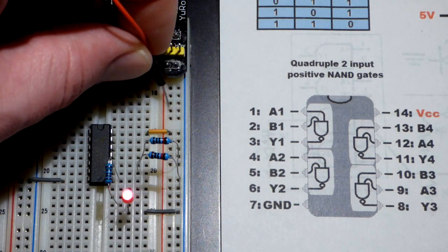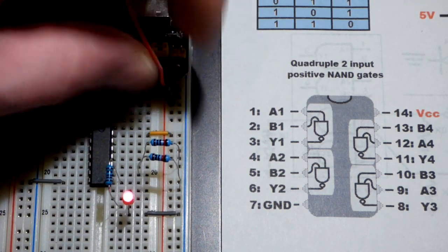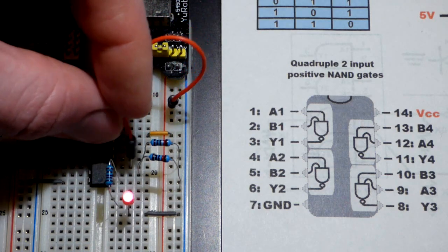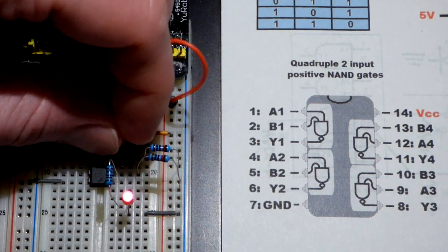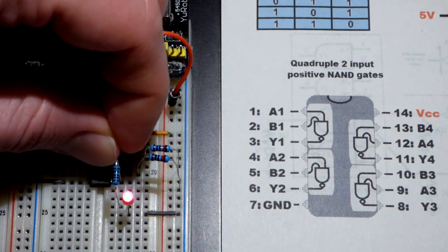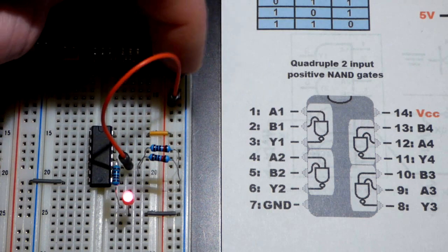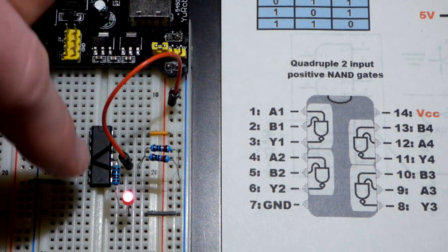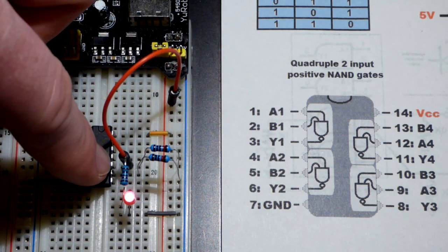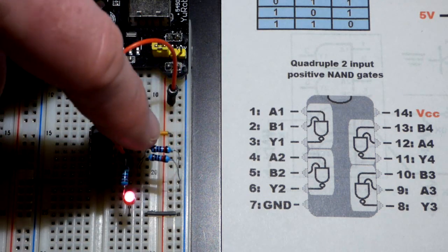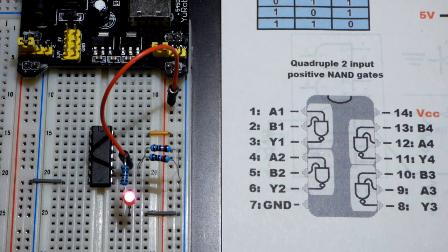So we will just directly connect a jumper to the positive rail there, and we can put it to either input. Let's do this one first. You can see LED is still on. If I jump it over one, of course the LED is still on. So right now we're directly to the positive rail over to there. So the pin is getting a 5-volt signal there because the resistor is going to hardly absorb any of that energy.